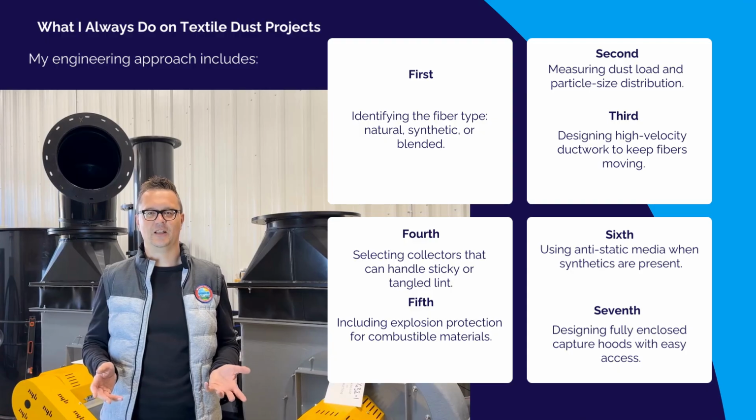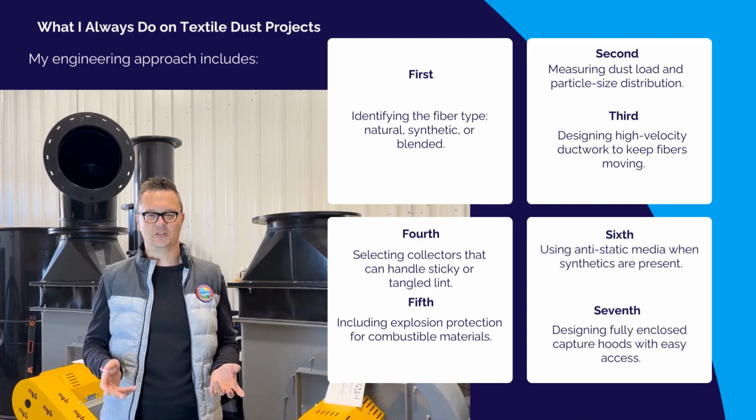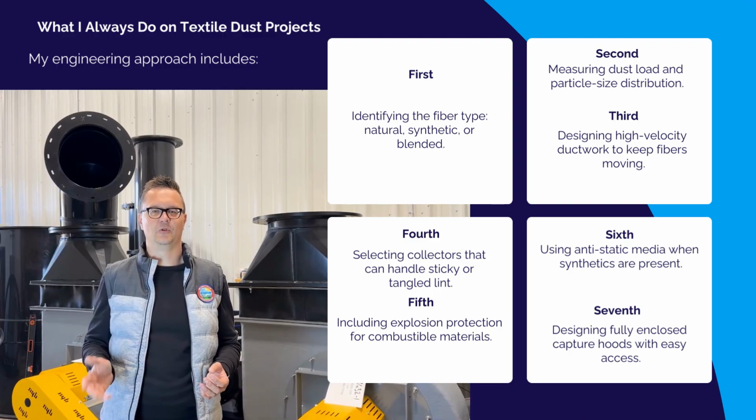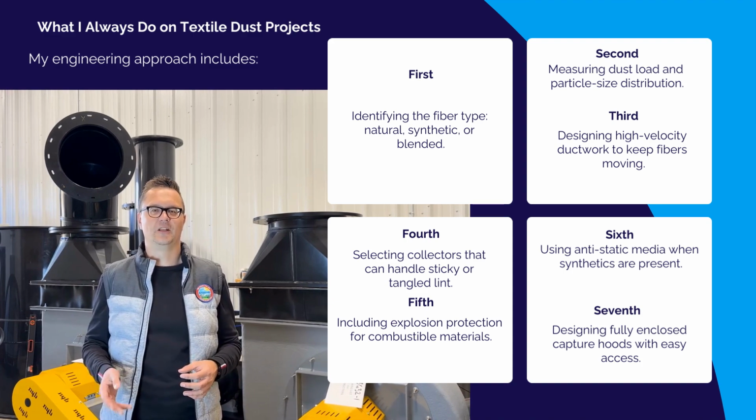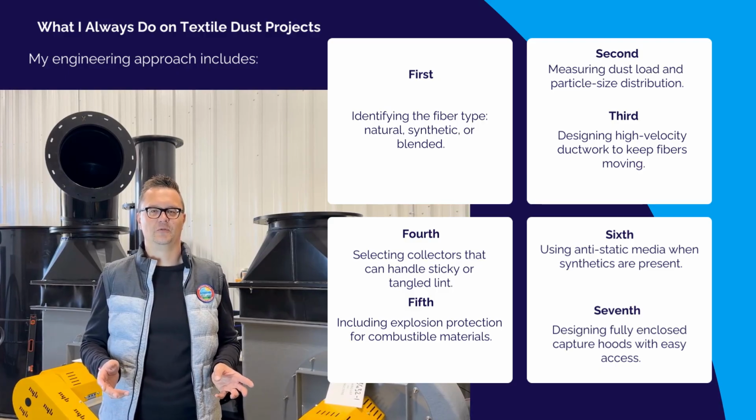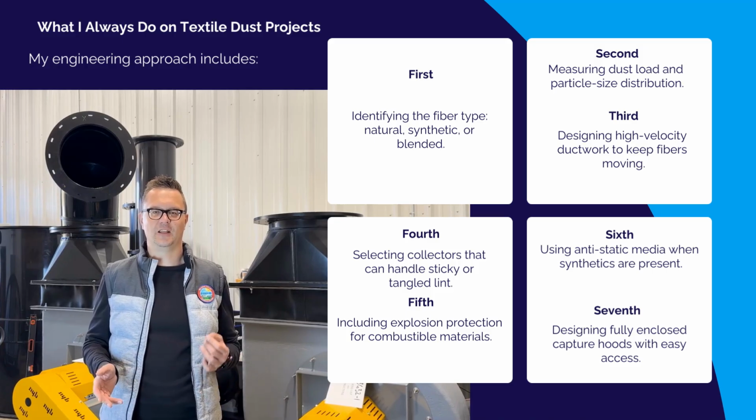What I always do on textile dust projects. My engineering approach includes, first, identifying the fiber type: natural, synthetic, or blended. Second, measuring dust load and particle size distribution. Third, designing high-velocity ductwork to keep fibers moving. Fourth, selecting collectors that can handle sticky or tangled lint.